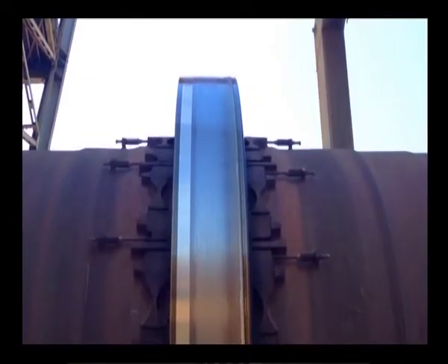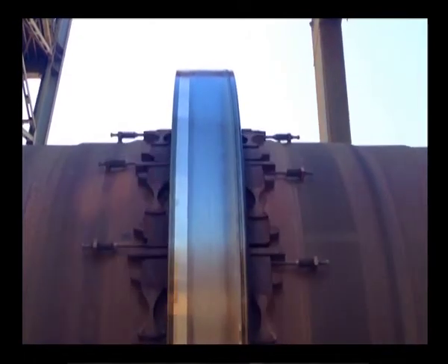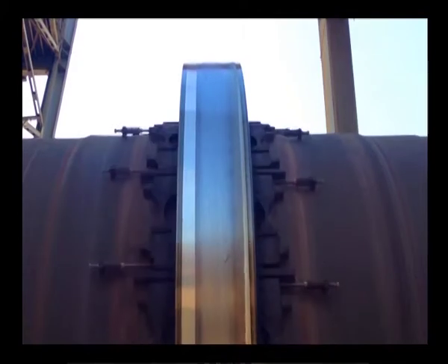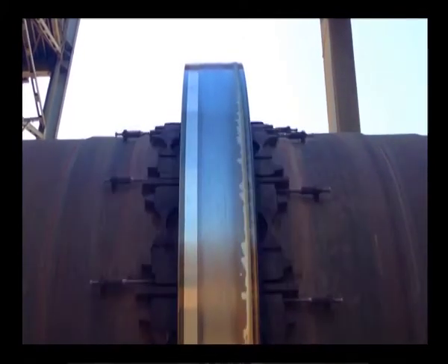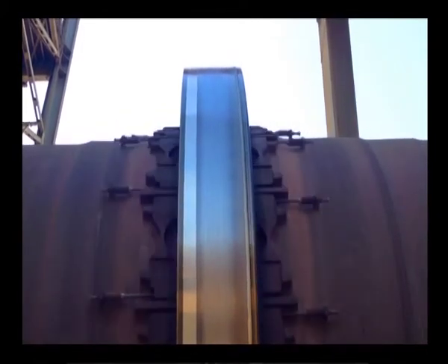In its classical embodiment, a kiln is comprised of a steel cylindrical shell lined with abrasion resistant refractory to prevent overheating of the metal. A kiln is generally inclined slightly toward the discharge end, and the movement of the solids being processed is controlled by the speed of the rotation.